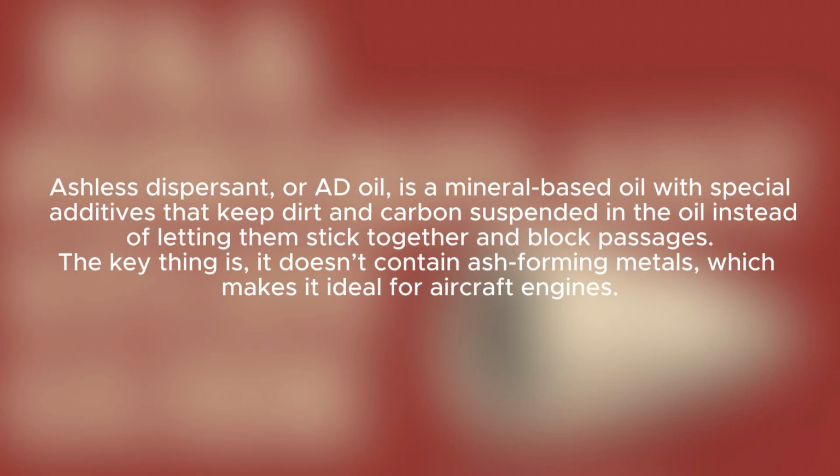So what's different about ashless dispersant oil? Ashless dispersant, or AD oil, is a mineral-based oil with special additives to keep dirt and carbon suspended in the oil instead of letting them stick together and block passages. The key thing is it doesn't contain ash-forming metals, which makes it ideal for aircraft engines.